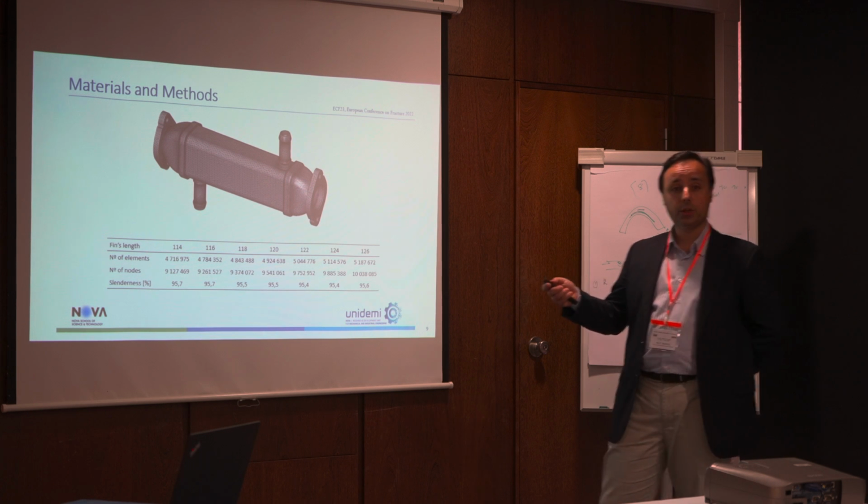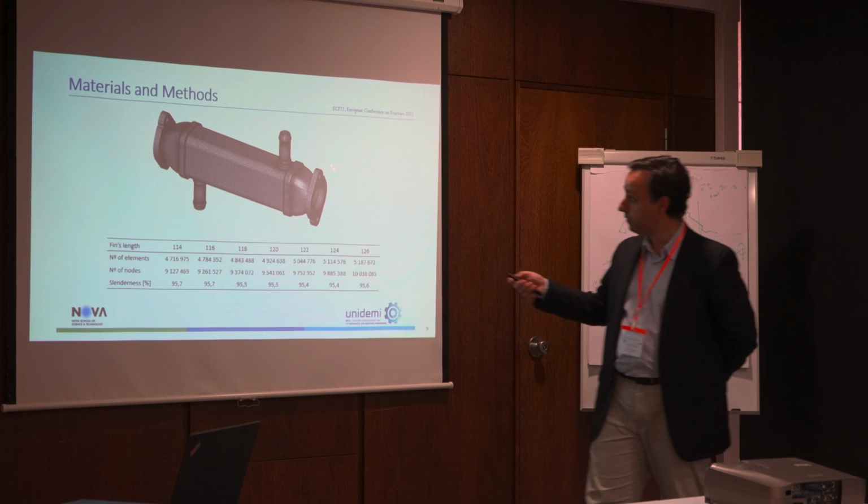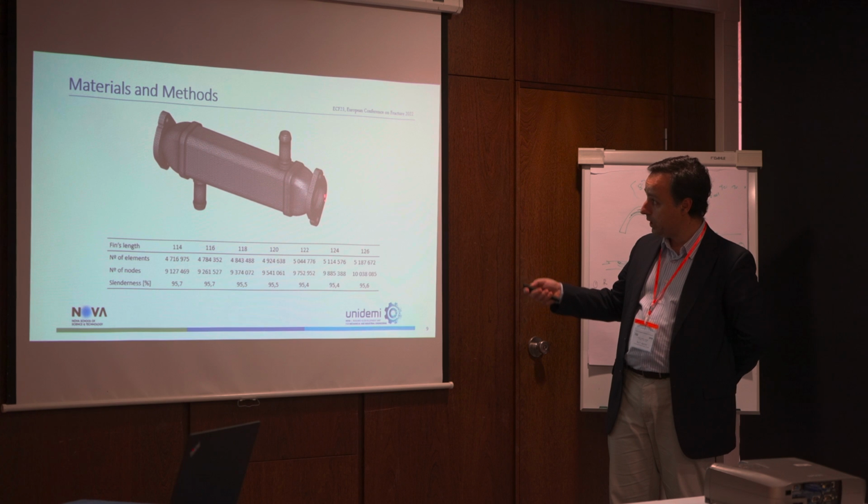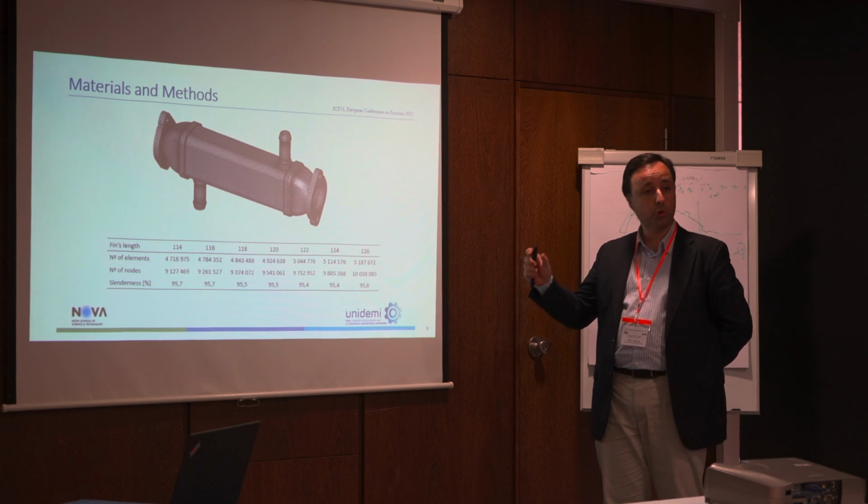About the boundary conditions in the thermomechanical analysis, we defined that the flange and these bolt-through holes were fixed in order to avoid rigid motion of the system.